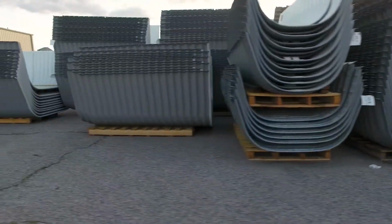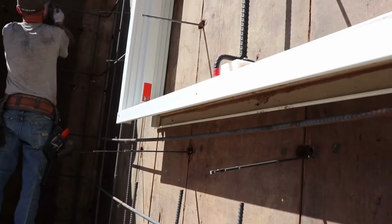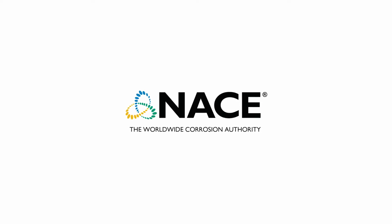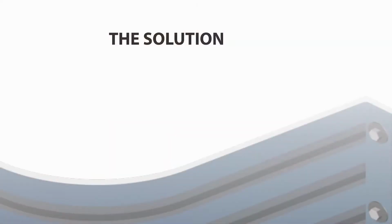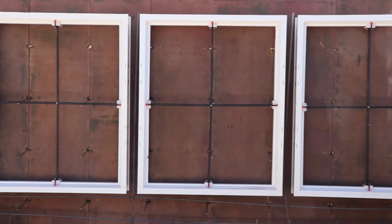QualCorr's research helped us to identify exactly what was causing the window wells to corrode. Their subsequent recommendations are based on the National Association of Corrosion Engineering standards. In summary, there are 2 things to do to help avoid the creation of a corrosion cell when installing an area well. Number 1, position rebar around a window in a way that the rebar won't make contact with the buck or the mounting bolts.